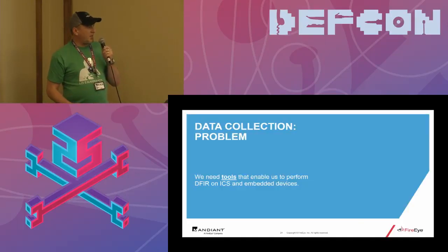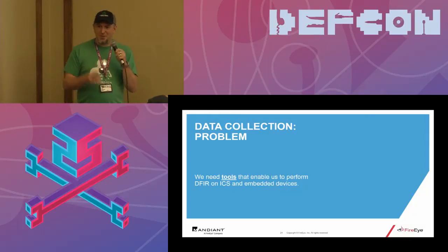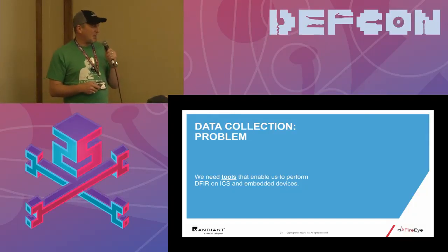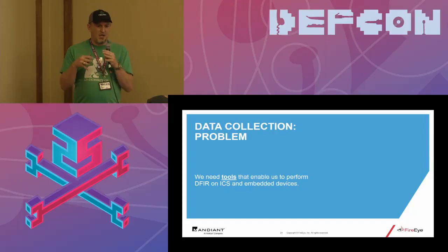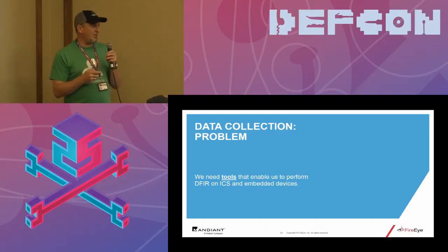Then we can do D and dump the memory, and we see DEADBEEF when we dumped it. There's no live demo here, we just took screenshots. So we show that if you are an attacker and you have console access to this RTU, you can inject memory, just like you can do with Windows or Linux or whatever.